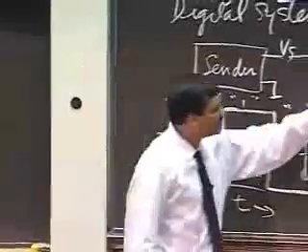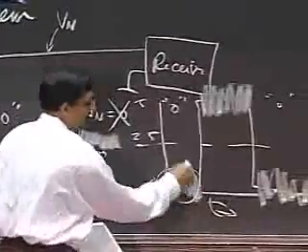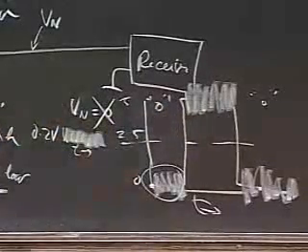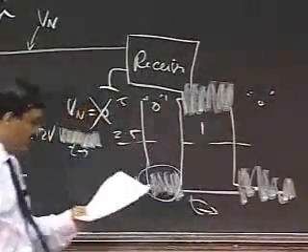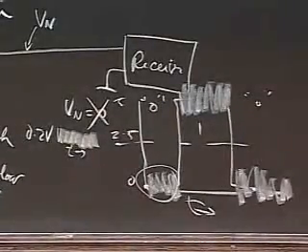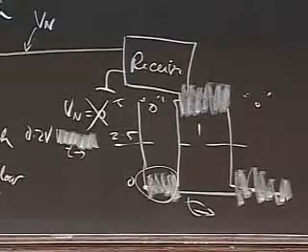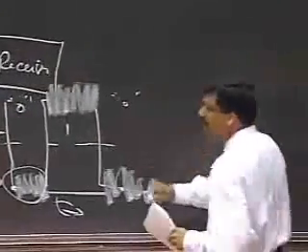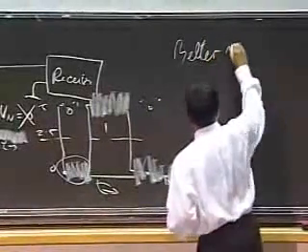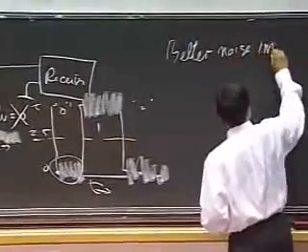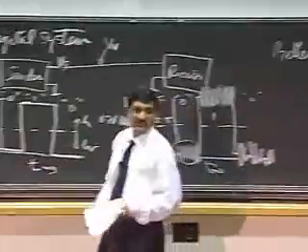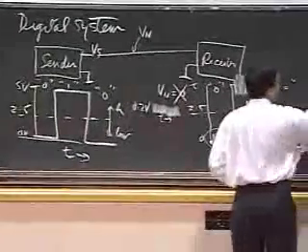But guess what? No problem. The receiver says, oh yeah, this is a 0 because the values are less than 2.5, this is a 1, and this is a 0. So 0, 1, 0. Here my receiver was able to receive the signal and correctly interpret it without any problems. Because I used this value discretization, and because I had this agreement with the receiver, I had better noise immunity. Consequently, I had what is called a noise margin.